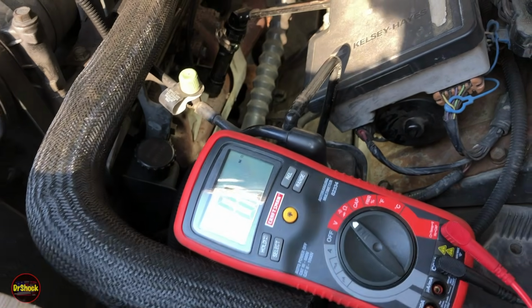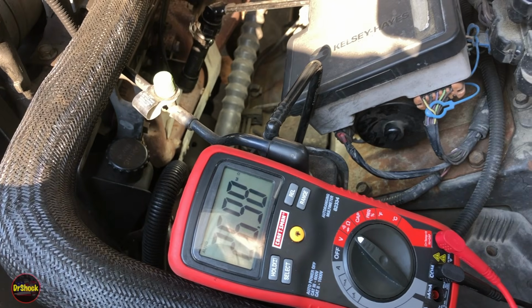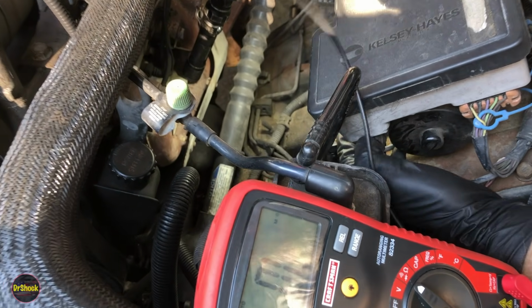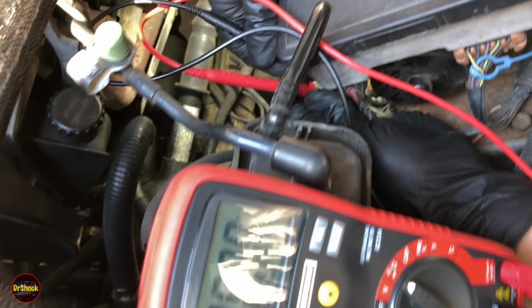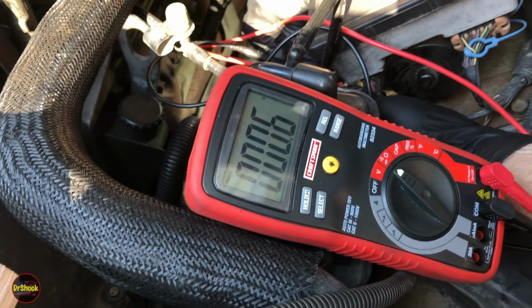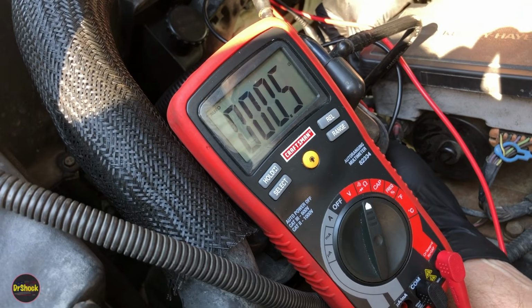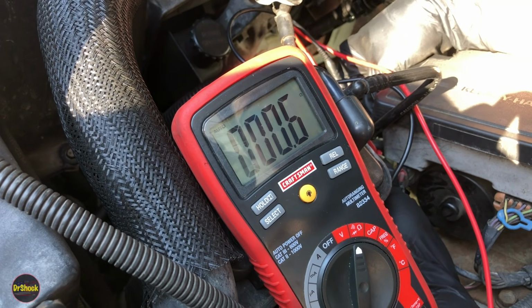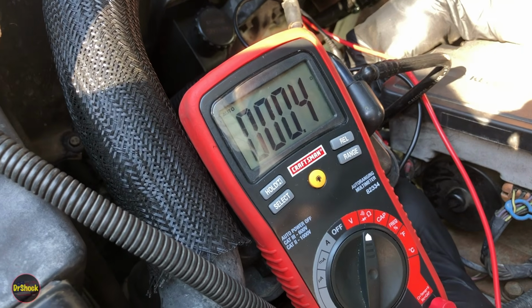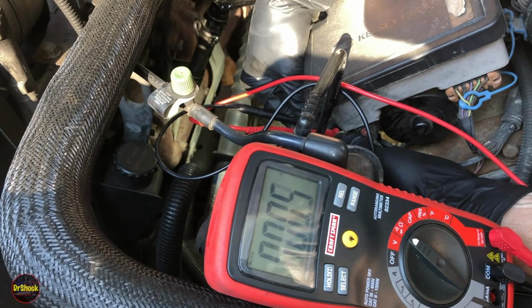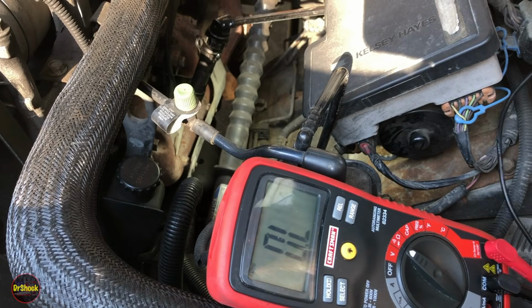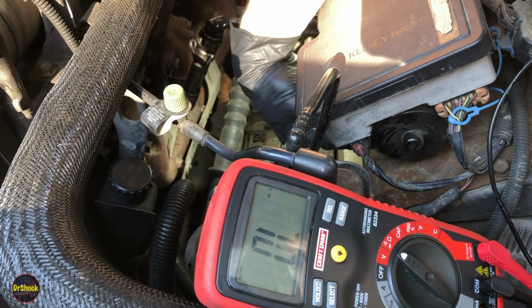All right, and then we're going to grab our ohm meter, bring it down where you guys can see. And we're going to do a test of the resistance between the two terminals to the pump motor. Here and here. Make sure you got the key off for this test. And we want a value between 0.1 and 1 ohm. And we got 0.6, 0.5. It's bouncing around a little bit because my hand keeps moving probably. Just going to hold it and make sure it stabilizes. Yep, 0.4, 0.5.